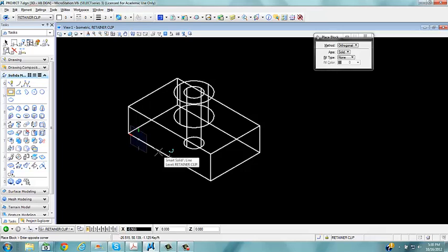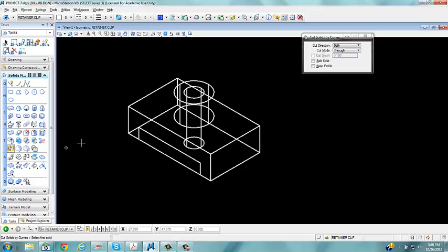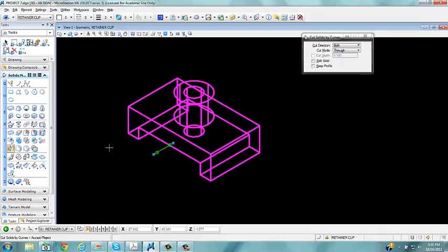The width of this is going to be 3, and the height is going to be, I had it written down, looks like we'll call it 0.5. And again, all this is a two-dimensional shape. We're going to use our same cut solid tool, select our object, select our shape, going to go all the way through and cut it.